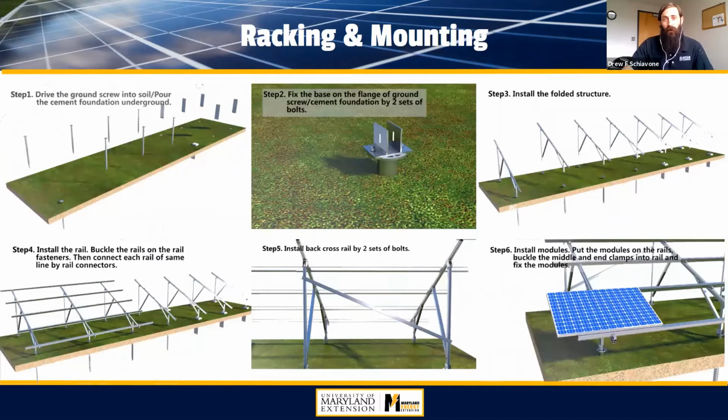Now, with the larger ground mounted systems, you're going to need more than one post, obviously. And so in this example, and this is just one option available on the marketplace today, this is a screw system, but you could do any kind of pier or pile driven into the ground. So this screw system, you're putting multiple points in. Again, you'll have to look at some of the structural analysis and soil analysis to dictate how many of those you drive into the ground.